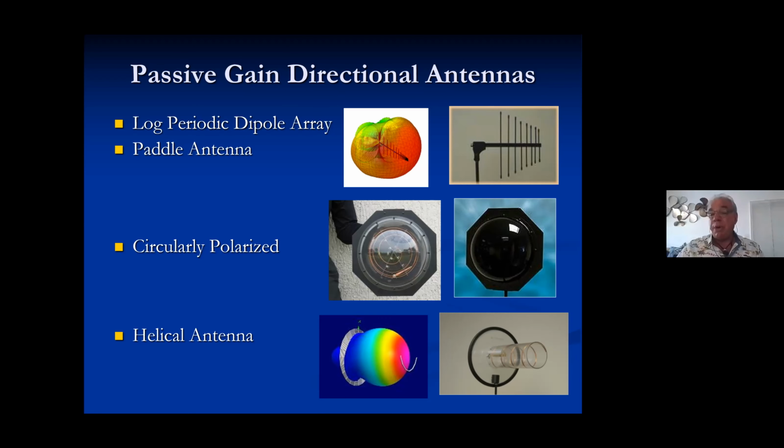These antennas are all passive. So in the case of the helical, which is the granddaddy of them all, you get 12 dB of gain over a dipole, and that's passive. Well, that's as much gain as an RF amplifier that's adding at least 12 dB of amplifier noise from the electronics in the circuit, right? So I'm always going after passive gain.